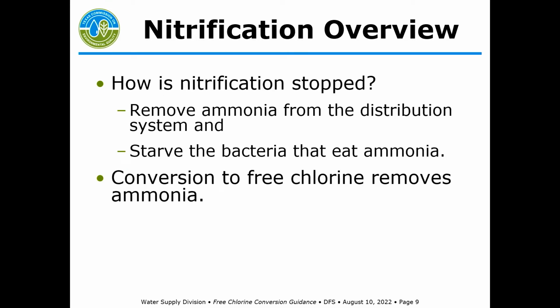So how do you stop nitrification? You have to remove the ammonia from your distribution system, and you're taking away the fuel, and you starve the bacteria that eat ammonia. And the conversion to free chlorine does eliminate all free ammonia in the distribution system.